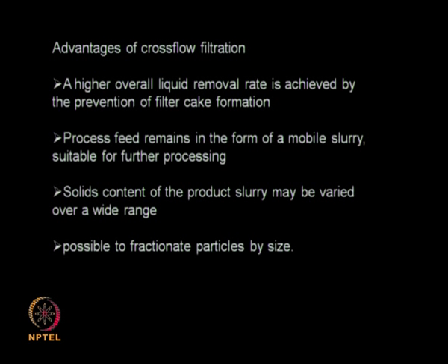So advantages, as I said, removal rate is very good and it prevents the cake formation, and the feed remains as a mobile slurry, unlike a normal filtration where you have the solids and the slurry sitting on the solids. We can look at different percentages of solids present in the slurry, and it can also do fractionation of the particles by size. That means I can get solids of different sizes separated using this type of approach.